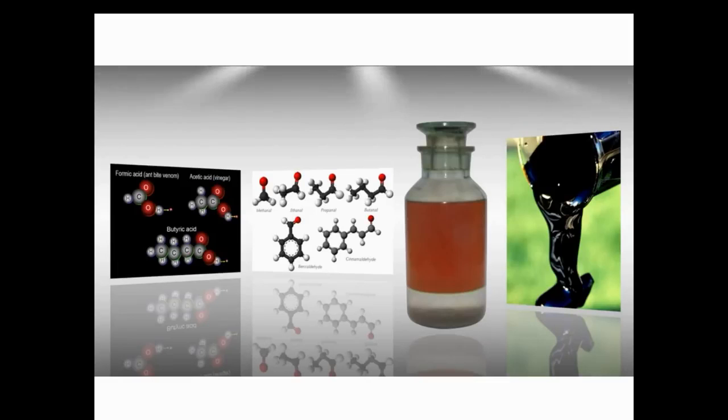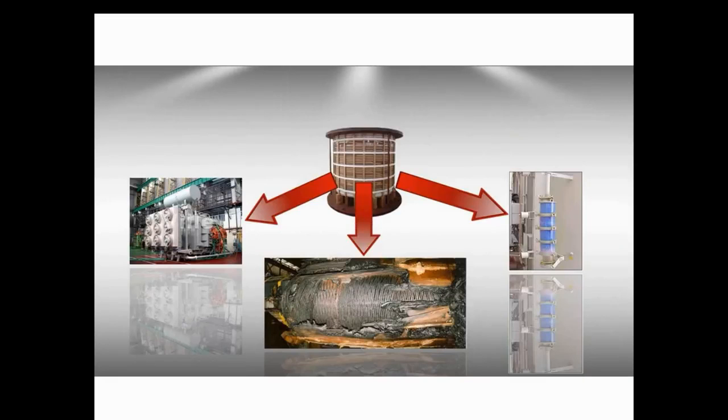And now we are back to the paper again. Transformer paper acts like the paper in a car's oil filter. It filters the above decay products out of transformer oil and holds them, destroying insulation. Now I'd like to speak about moisture affecting a transformer. Moisture comes to cellulose basically from 3 sources.